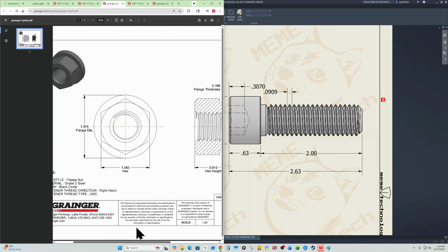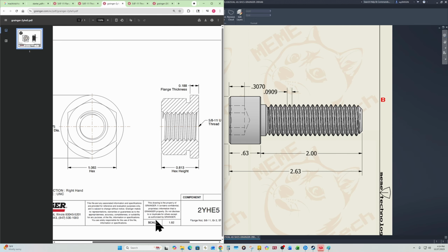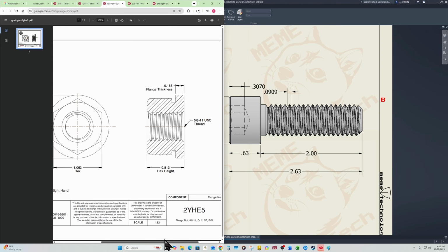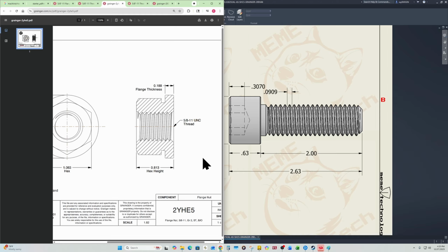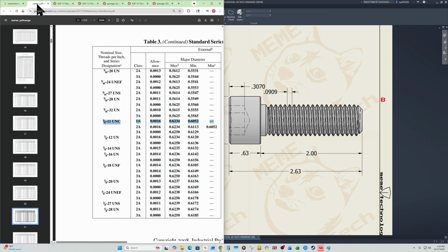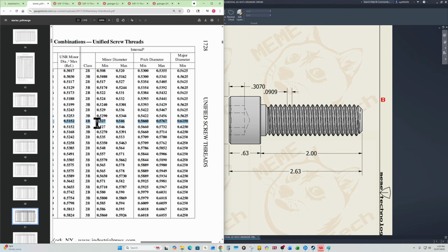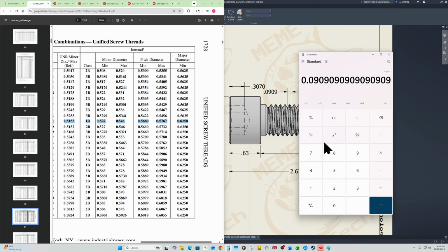Okay. Cool. So one thing we can do, we can Google the tap drill chart. That's one way to do it. And for 5/8 by 11, off the top of my head, it's 0.531, right? I think it's 0.531. We'll just calculate everything. So we got the minor diameter between 0.527 and 0.546. So yeah, 0.531 is definitely inside of it. It's not the middle, but it's bigger than the minimum and smaller than the maximum.